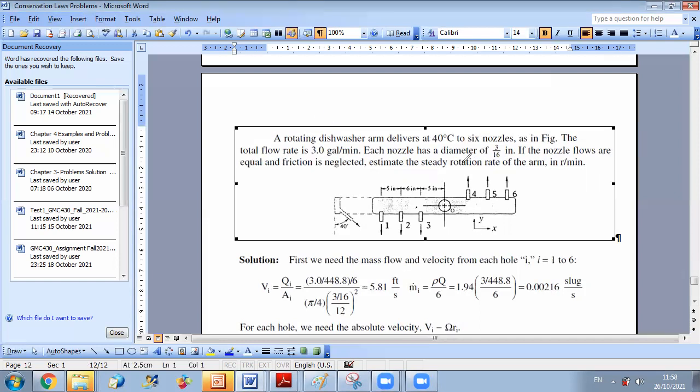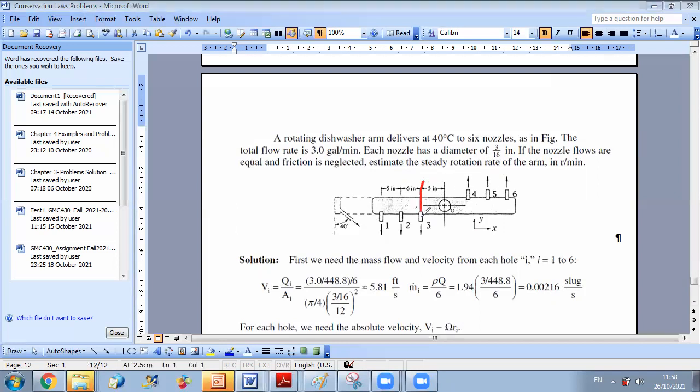So under the effect of the jet, as you are getting the jet out, this will cause rotation of your arm, and the direction of rotation will be opposite to the direction of jet exit. To understand this more, it's like the effect in rockets. In rockets, when you expel gases backward, this will drive your rocket upward.